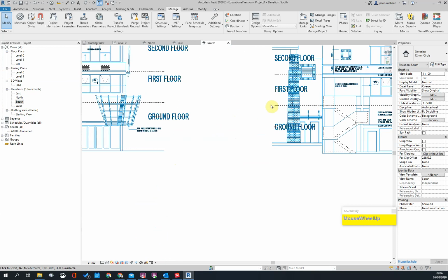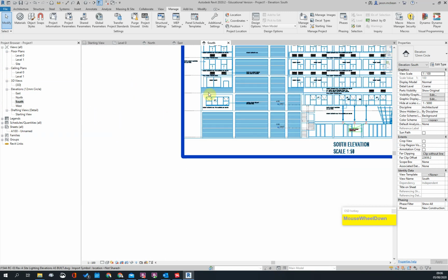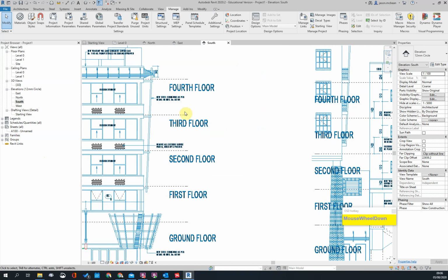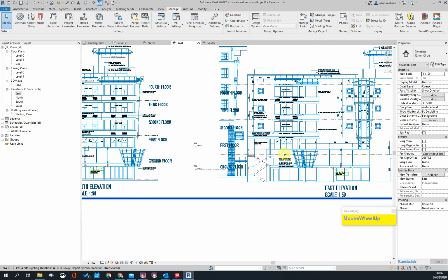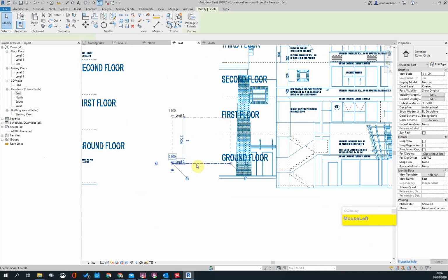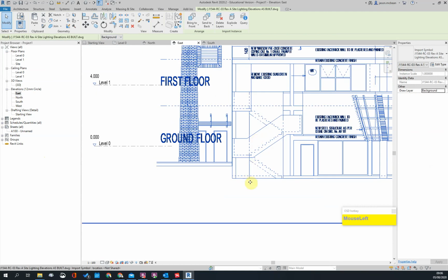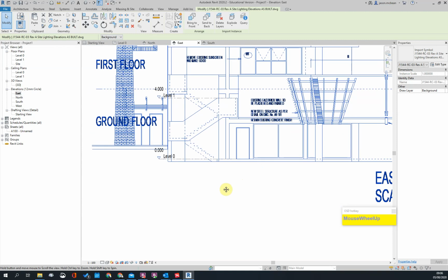And if I look here very quickly, these levels should start lining up, and you can see in this they have kind of highlighted the levels that you want. So they've got 4th, 3rd, and I'll just go to East View, and I'm just going to double check something with these elevations. Here are my model's levels, so I might need to move this drawing. I'm going to move this level to match this level for the time being.